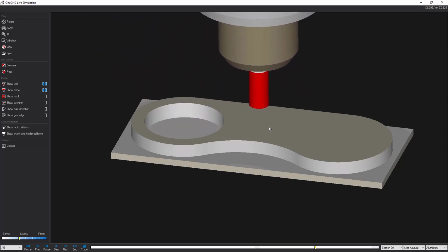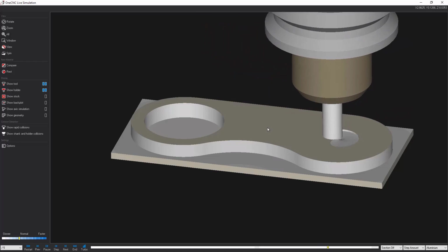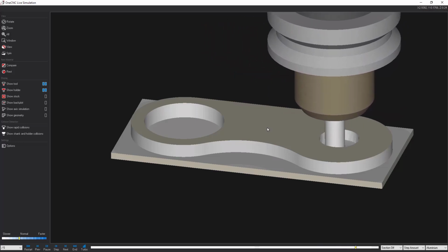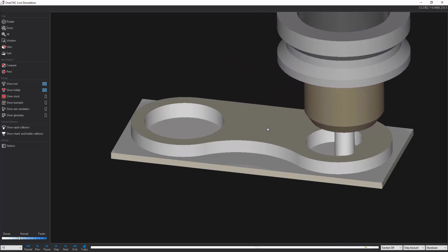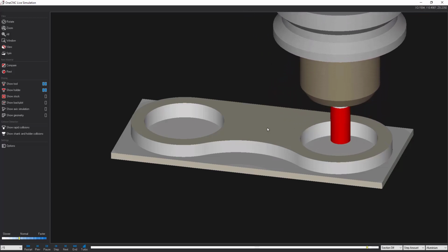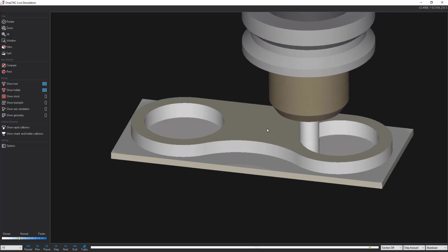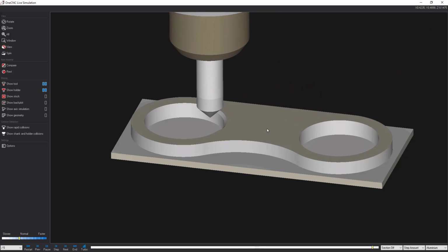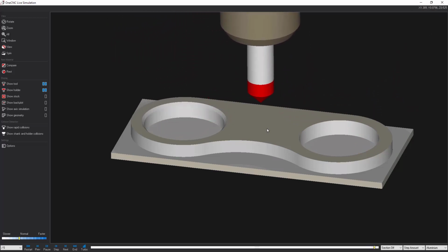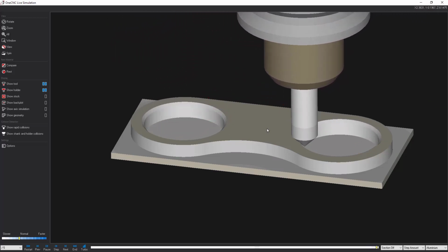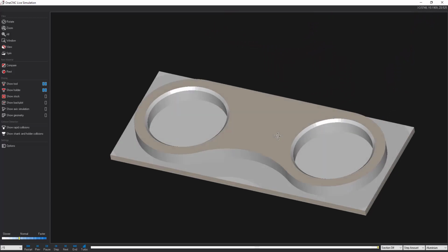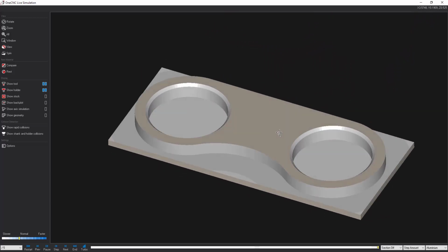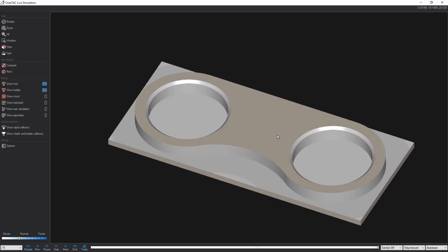That's where we kick the RPM up. So a helical approach, all the way to depth, perform the roughing in a spiral fashion, leaving the amount for our finish pass, which you see right here. All right, now so here's our chamfer operation. Very good. All right, so we've applied our machining operation for this portion of the toolpath.